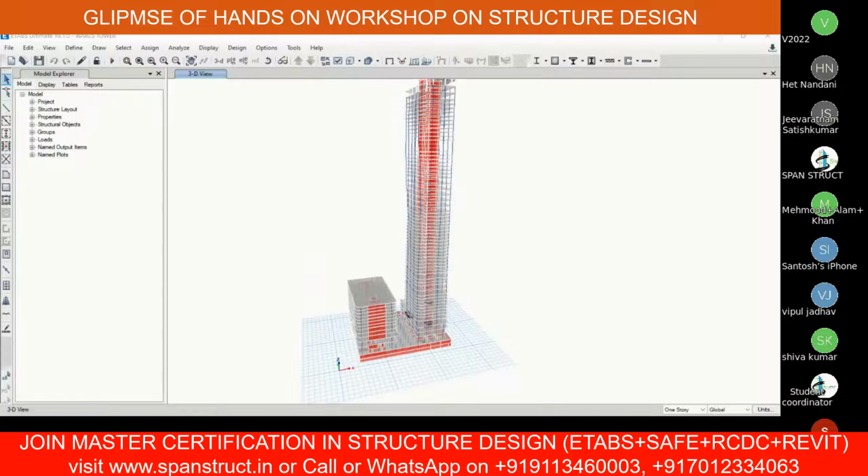So through that also you can directly start modeling the ETABS in ETABS. Basically, if you're having 100 projects, in that 80 of the projects you will be doing through .dxf floor plan. This is a very common way of doing the structure modeling, importing .dxf floor plan. And for a few projects, like smaller structures, you can take the help of the grid lines.